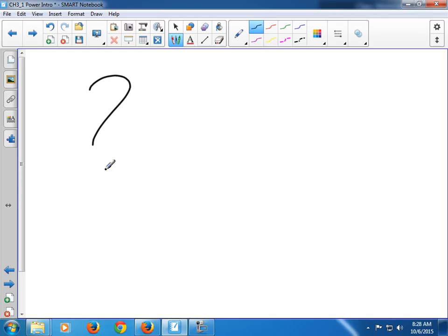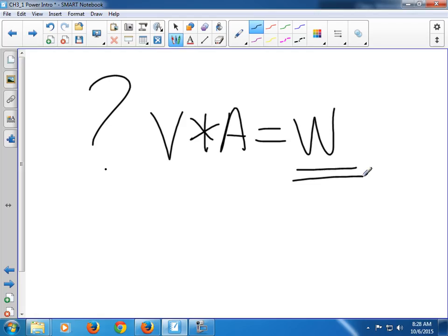So we know that volts times amps equals watts. This is the important number. We need to know the total wattage that a PC uses. You always know the voltage because that's the potential of the plug. This plug has a certain potential, and then the device will pull some amount of power when it comes inside a computer. So potential, current, total. Potential, current, total. You got that, kind of?